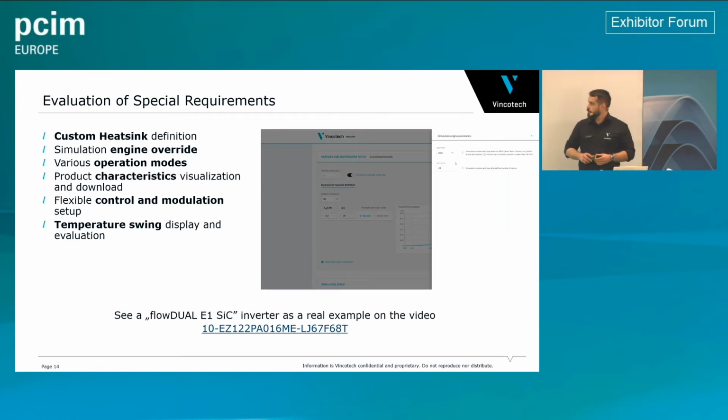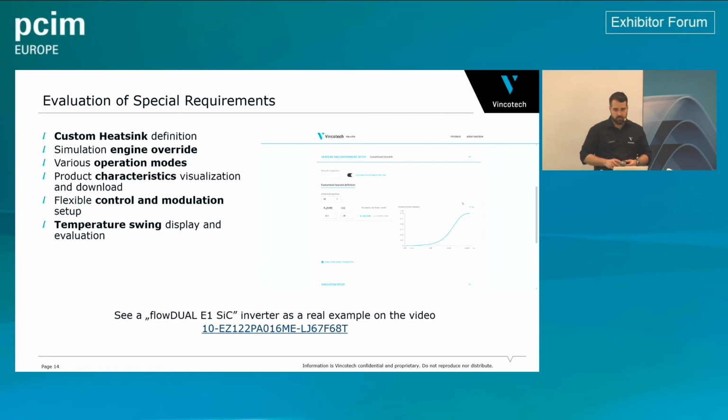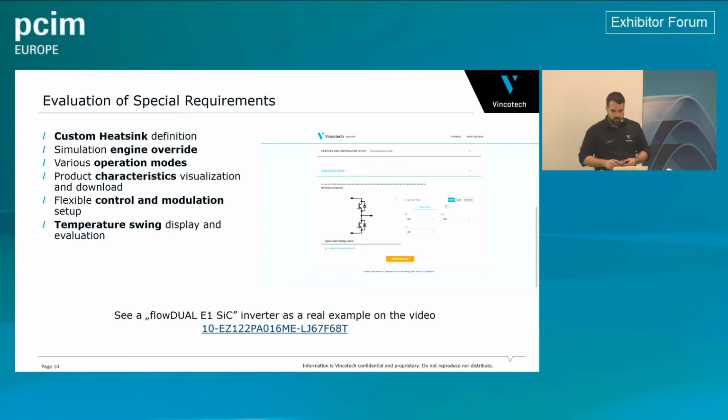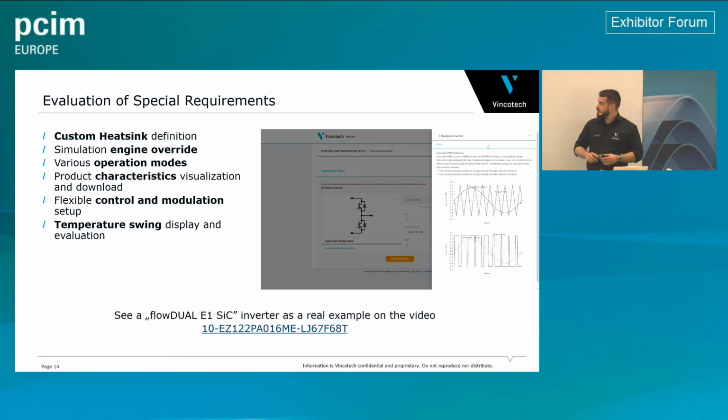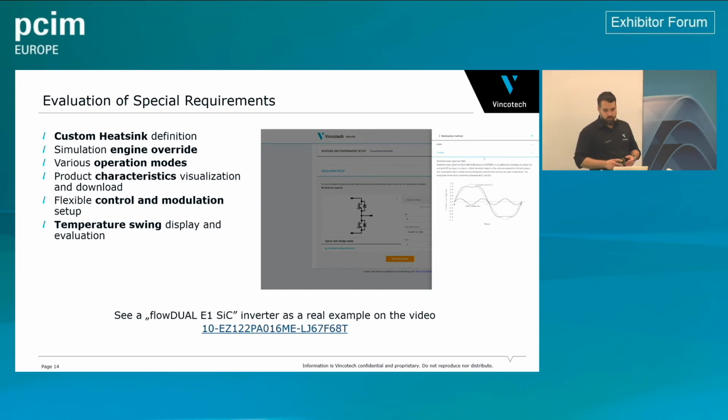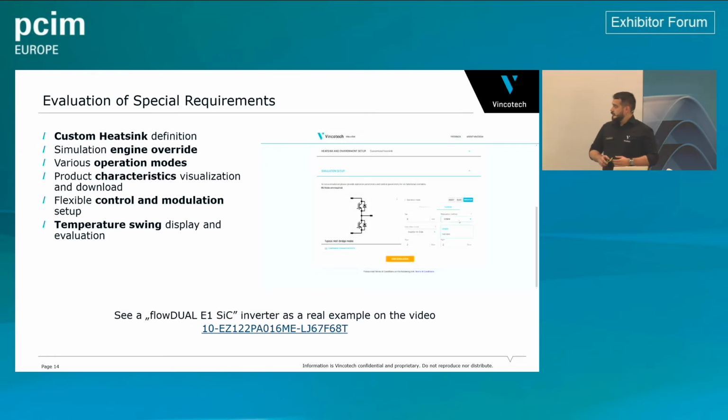If some problems are with the convergences, you can adjust later the simulation engine as well, so the convergence criteria can be defined. And then you can configure, of course, again, your half-bridge. Here you see 3 different operation modes. So basic DC-DC and the DC-AC operation. If you have any question, then you can open the help for it. The steps are the same. You set the parameters, select the proper options, and then you will execute the simulation itself.